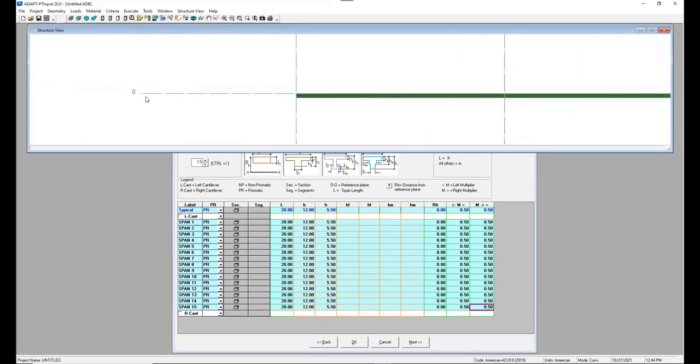If you notice, we have the 0 here, and this is our datum. And that's what this next column is talking about. And in PT design, when you start getting into your drafting and detailing, typically the tendon heights, the CGS or the center of gravity of steel, is referenced from the bottom of the slab.